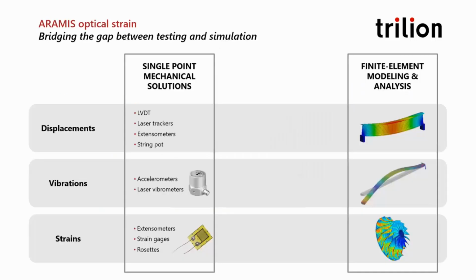So typically labs use instrumentation like LVDTs, extensometers, accelerometers, foil strain gauges. These are all contact sensors at single points, many of which collect a lot of data, maybe a few thousand times per second. So they give you 1,000 values at one location, just a single location. Possibly by placing this on the surface, you could disturb the local mechanical response of the material. This is especially true for soft tissues within biomedical. And you're really only getting this discrete location of data, not the global strain information.